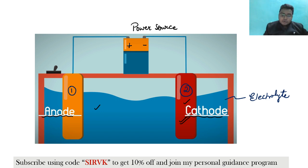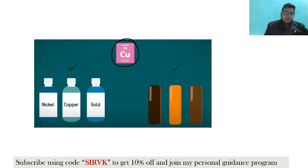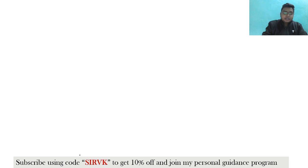So if you want to plate this material with copper, definitely the anode that you take will be copper. Also, the electrolyte should be a copper based electrolyte. This is one of the criteria that I wanted to tell you. Suppose you want to electroplate a material with copper, then the electrode you take should be copper, as well as the electrolyte should be a copper based solution. Suppose you take copper sulfate, which is a copper based solution. Now let's try to understand this.